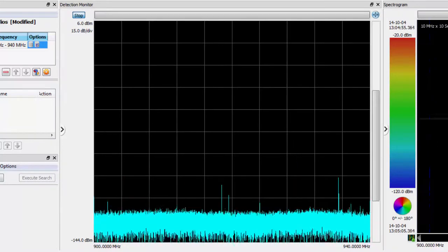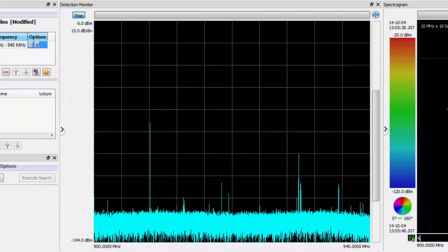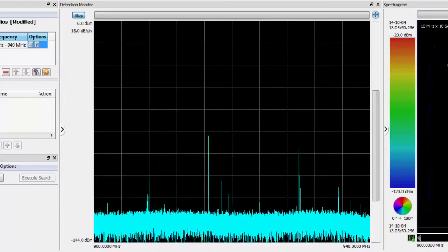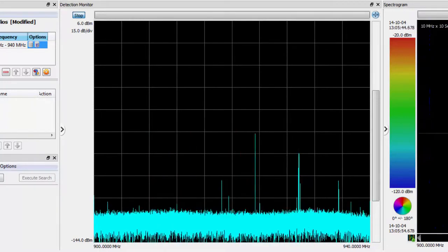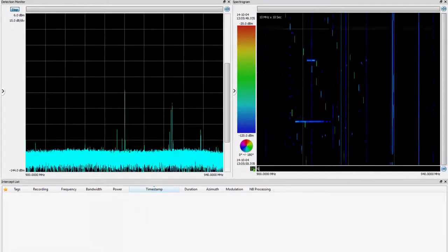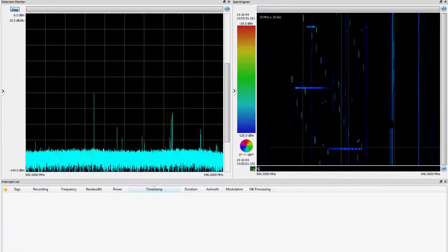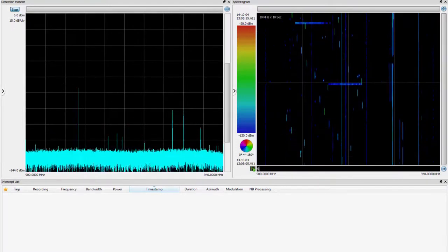When a frequency-agile radio starts transmitting, here, it can be recognized by the appearance of short transmissions which follow each other. As soon as one signal turns off, it is replaced by another. This pattern of behavior can be seen even more clearly on a waterfall display like this spectrogram. The frequency-agile signal is easily recognized by the appearance of short vertical dashes that show the transmitter jumping from one